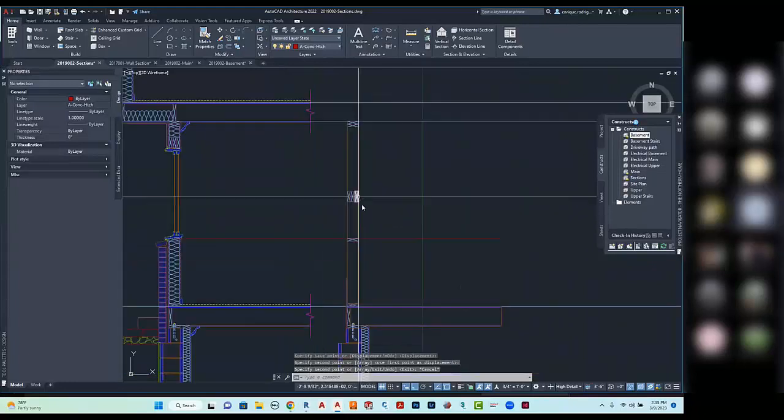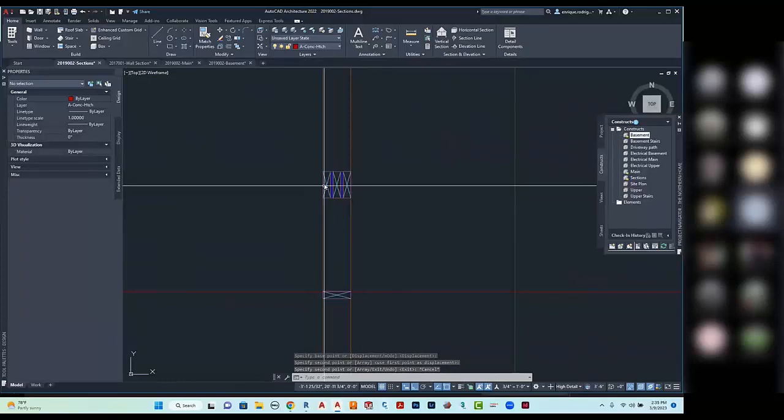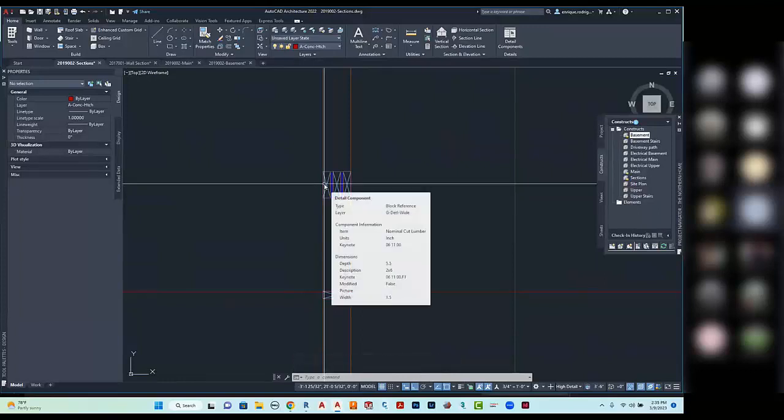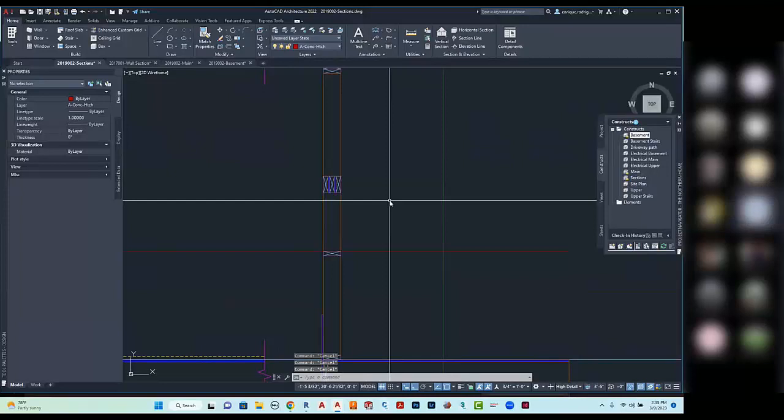This creates a solid header where the vertical direction for the wood is stronger than a horizontal direction. So it allows all that load that is on that window to span to both sides. And the fact that you're using 2x6s or 2x8s means that that is not going to flex. There's not going to be deflection on that beam. If it curves, guess what happens to the window? It may not work, may even crack, depending on what the design is for that load.